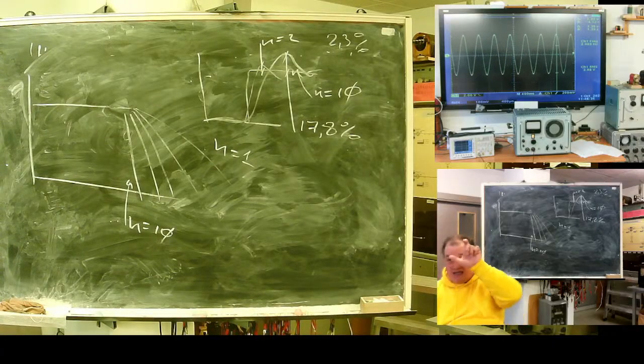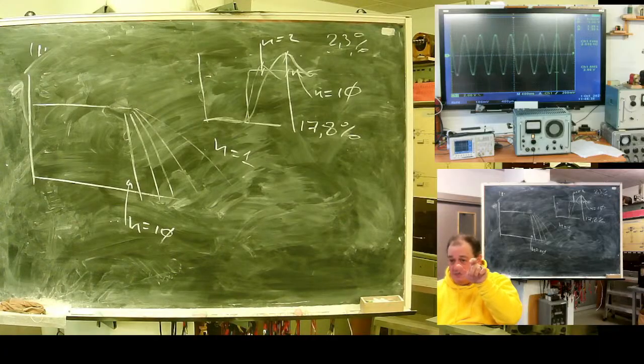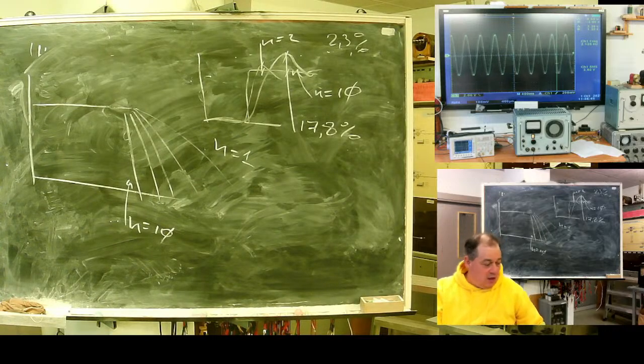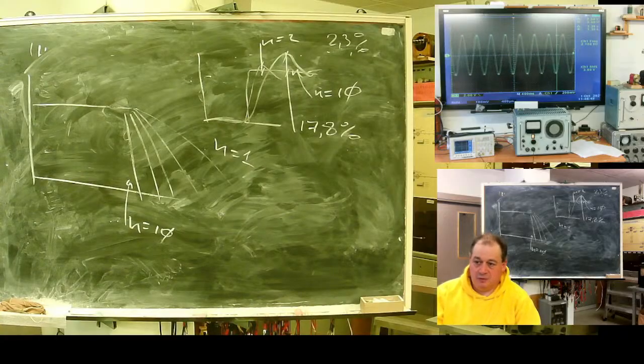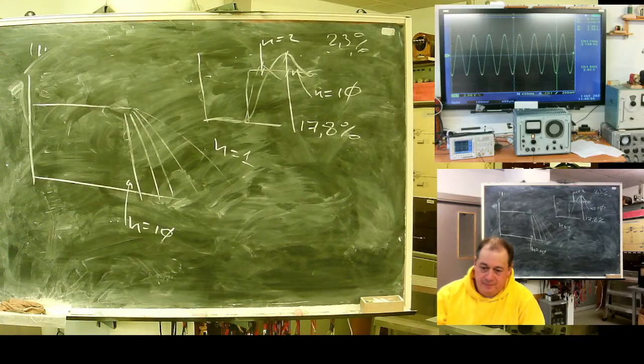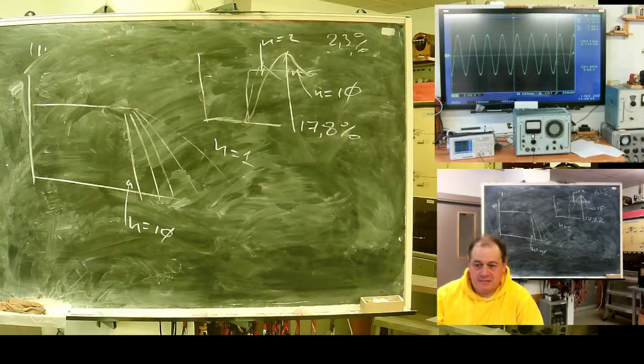The simple RC design worked at 50 Hz, but when we needed 250, the error was above 20%. Not the best design. Honestly, it's cheap. When you need the fifth harmonic, it's a good indicator of current transformer saturation. Okay, I will stop for now.